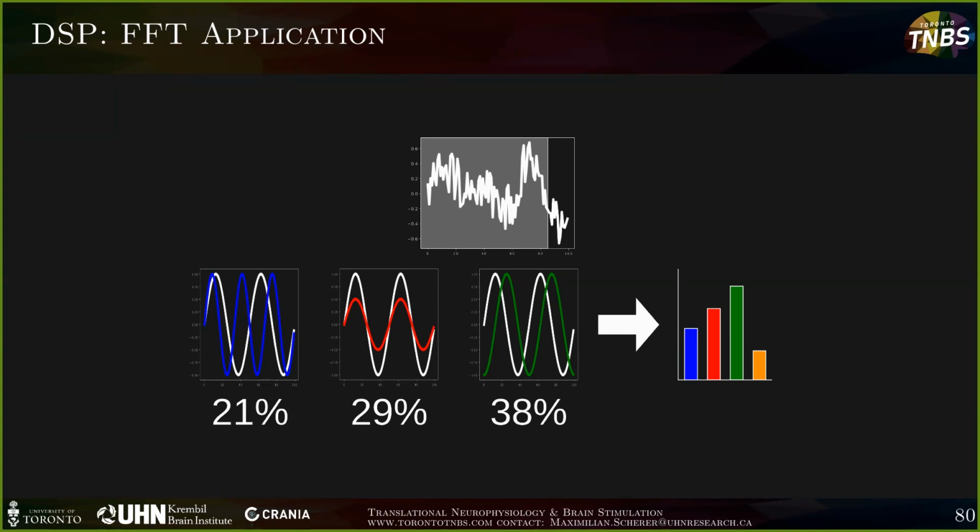And if you provide it with a really large window, you're going to make those frequency bins smaller, like 2 Hertz, 1 Hertz, half a Hertz, the more data you provide. And actually, by providing it more data this way and having a higher quantity output, you're introducing even more noise into your data because you're running into the issue of data sparsity. And you're not going to get a smooth power spectrum density.